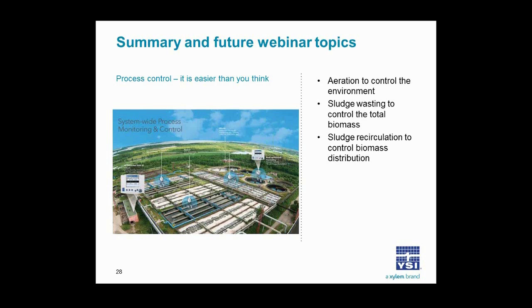Well, let's take the extreme example. If we had plotted those two lines and that intersection had fallen above the curve, so outside the curve, that is a very serious condition. That's clarifier failure, and basically all your clarifiers just become a white spot in the line. It's a complicated topic. I hope I've helped to answer that a little bit. But I'd be happy to address it offline with anybody that's interested.